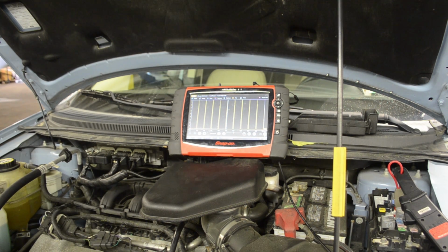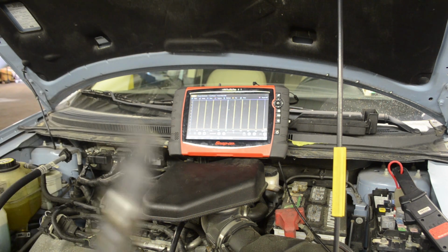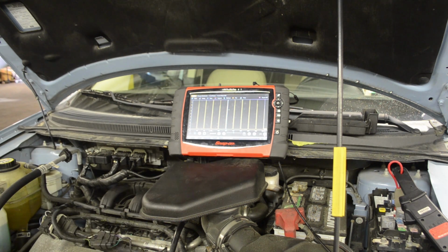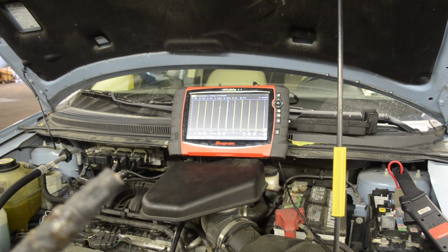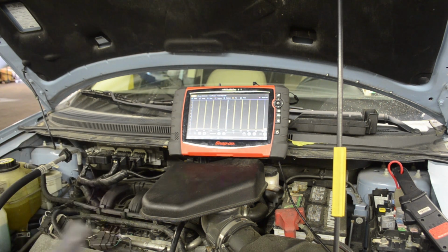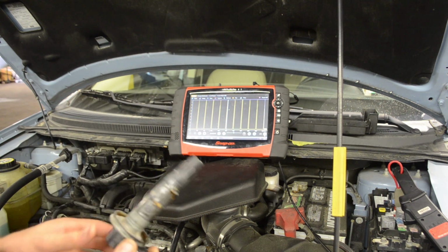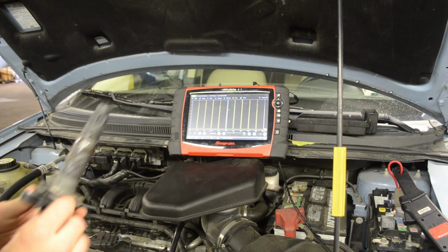Now, it's always hard to call a module, but in this case, if it would have been different, if I would have had a no spark and had no coil firings on any of the cylinders, and all my inputs would have been good, my cam and crank, then I would have gone on to doing power and ground checks at my computer. But this one wasn't too bad. Calling that a fix. I'm pretty happy I was able to actually fix this one and be able to show it. That was cool.